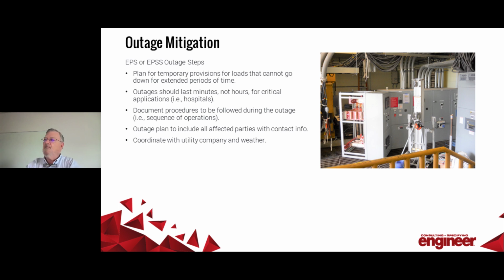Now, as we consider the implementation of these updated code requirements from old systems, we have to plan for outages. I get involved in a lot of healthcare facilities that have to have emergency power supply systems, and EPSS also expanded. The image here, for example, is generators wanted to be larger. Paralleling gear was too small to accept larger sizes. So instead of replacing the gear entirely, we decided to laminate extra layers of busing to take it from 2,000 to 3,000, a pretty neat option.